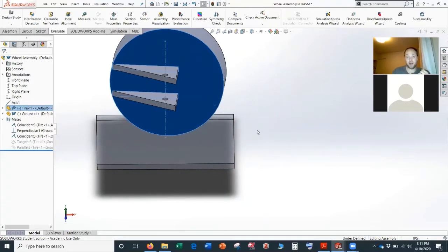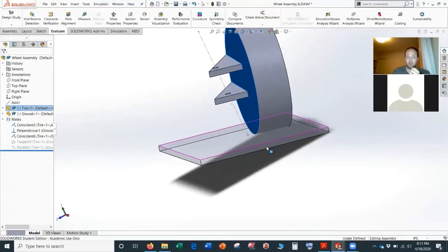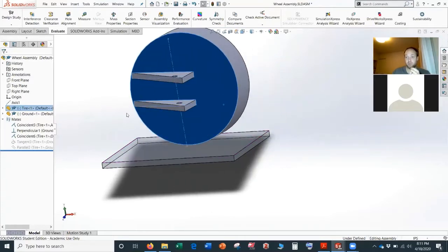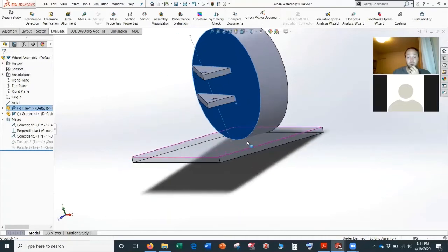the scrub radius. The scrub radius is known to give the driver a little bit of feel. So now you can think about it. The forces in the tire are acting around this axis. So whatever's holding your toe, for example, in the front would probably be like a tie rod to your steering. And in the rear, you might have some toe link. The more scrub radius you have, the more load that's going to go through it, especially on braking, for example. So braking is going to be large forces back, right? So if you have rear steering connected to the rear, you're going to put your long tie rods in compression, which might not be favorable. It might even be favorable to have front steering in that case to pull them in tension if you have large scrub radii.